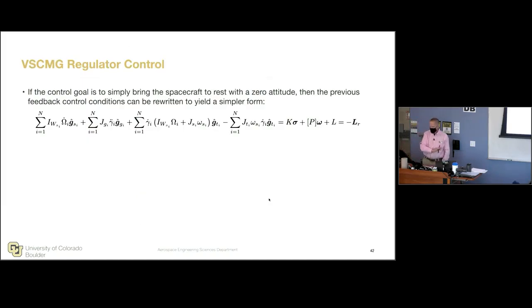This is for the tracking control. Like with rigid body attitude control, we developed the tracking control and had omega R dot, cross products. We also had to maybe feed back on omega tilde I omega, because it didn't just cancel out, or there was a trick where we could feed back on omega R tilde I omega that we showed, but tracking was always more complicated.